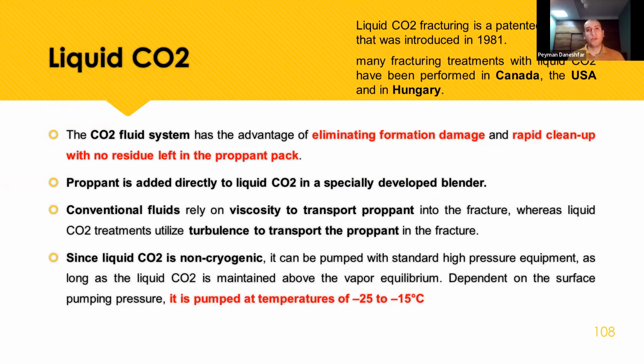It has a history. It has been patented. The process was introduced in 1981, and nowadays it is done in Canada, in the USA, and Hungary. And CO2 has some benefits: eliminating formation damage, and rapid cleanup with no residual left in the proppant pack. It's so important for us because it gives us good permeability between the proppant.